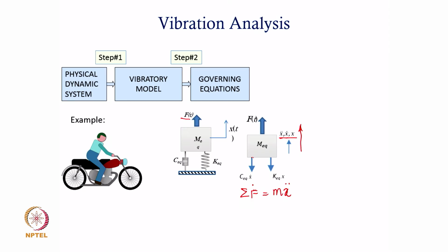Typically, all the forces in the direction of acceleration are equated to mass times acceleration, and the forces which act on this free body are the sum total of all the forces that I have identified here. So, if you strip the body from the surrounding, the damper is going to act its force on the body, and obviously if the velocity is positive upwards, the dissipating force, the dashpot force, is going to act in the opposite direction. We will discuss how these forces apply later, but this is how all of these forces are shown on the free body.